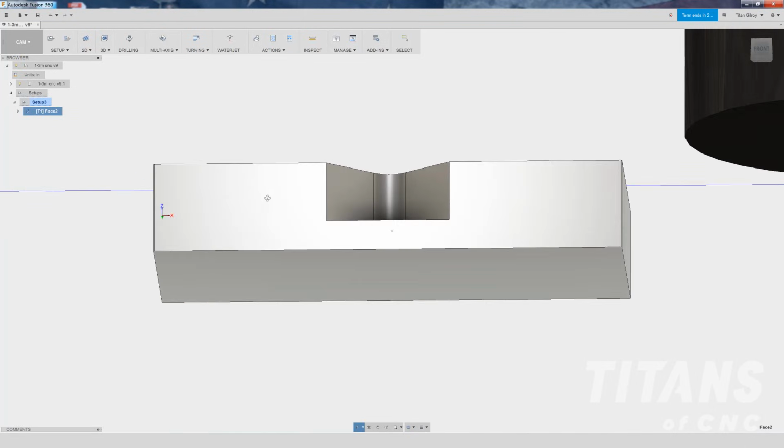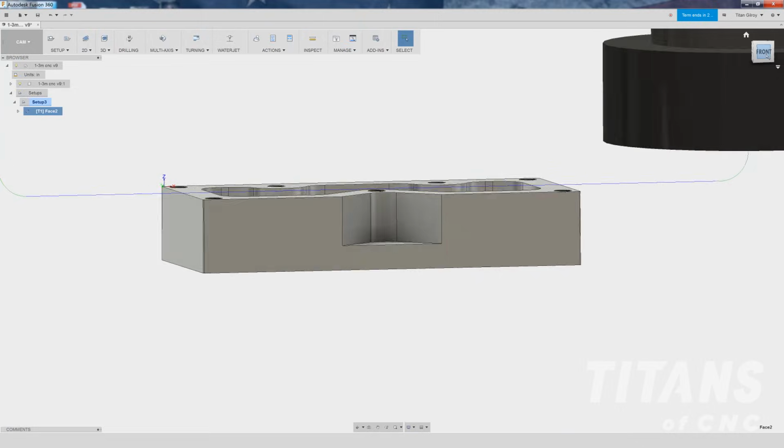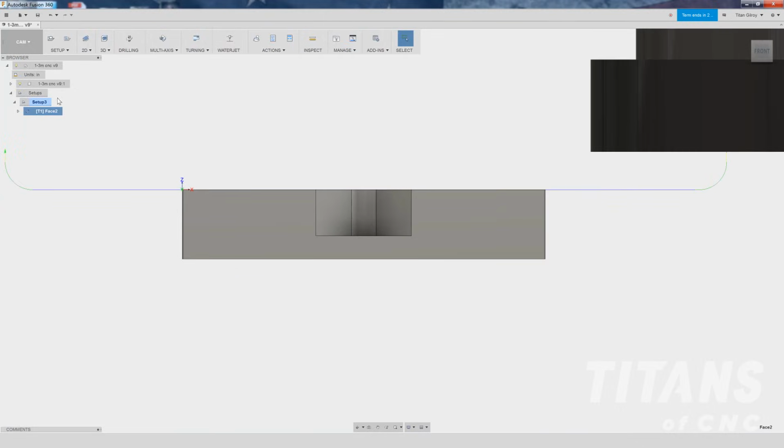So I'm going to look at the tool path. I can see that the tool comes down here, it arcs in, moves across, it's off the part, and it arcs up. If I wanted to, I can actually go in and make adjustments to the tool path. So just to show you how I would do that, face mill, let's just make that radius a little bit smaller. So I right-clicked it, I'm going to hit edit.